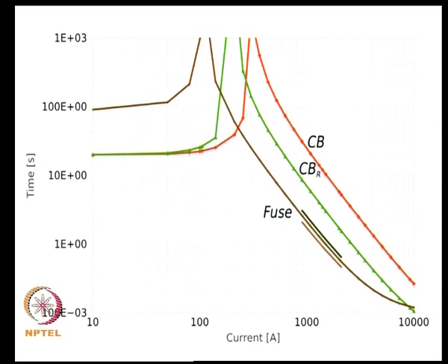If you look at the fuse, you have the nominal curve and then plus 20% I square T or minus 20% I square T. So, it shows up as a band around the nominal curve in the range of interest. If you look at the reset curve, you can see that the reset time also increases as you get closer to the melt time, but for many practical calculations you can take it to be roughly a constant number.